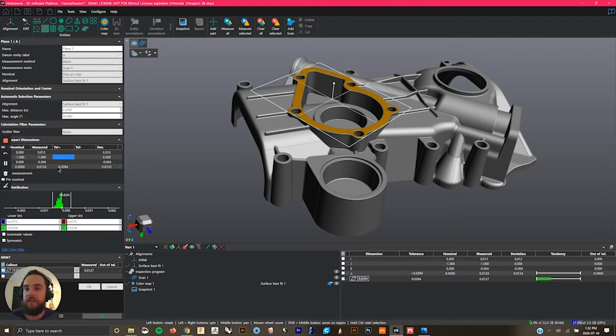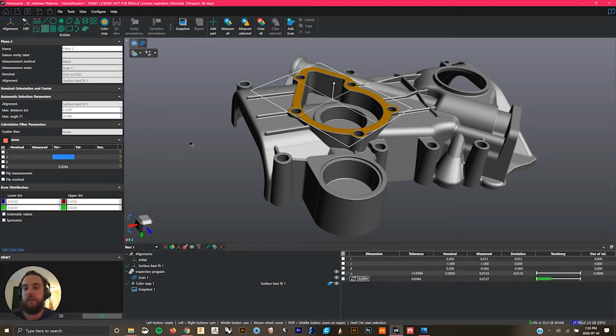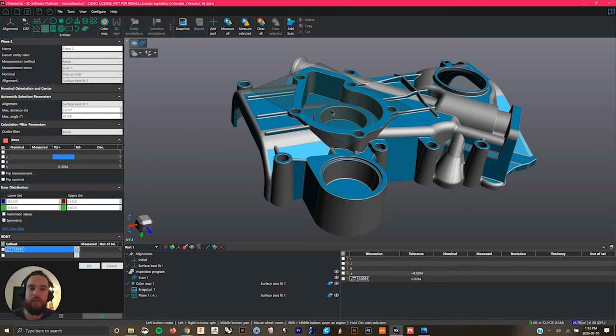All these different things here, too, are the different areas that this plane could report out on, and the different tolerances that you can program into each of those. Here's your variability. And then the surface profile callout, this is a GD&T callout. We can leave this if we need to, but because this is a datum, we could also delete it. But I'm just going to hit OK for now. So you can see a plane now is hovering over top of our CAD. So that plane is going to measure itself against the mesh every time we drop a new mesh in to report, and that plane is going to give us this particular reading, which we can find also if we select the plane in the viewer.